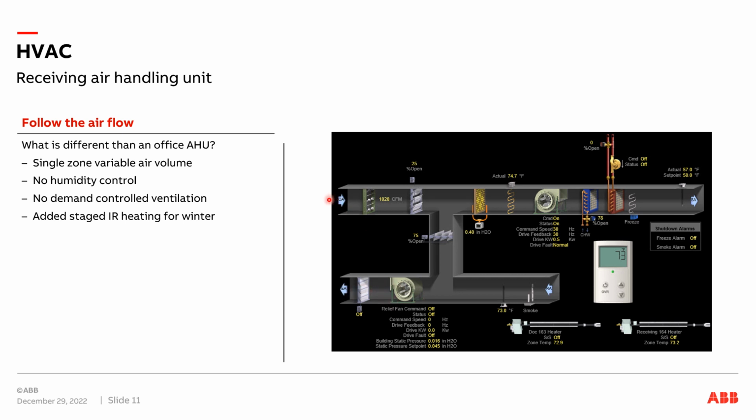So when you're bringing a lot of fresh air into the building, that air has to get out of the building somehow. Right now, with this being closed, I can probably tell that we have some big doors open and a semi-truck backed up, so there are other ways for the air to get out of the building. Had this been open and this fan been running, that would have told me all our garage doors were shut, so we needed a different way for the air to exhaust from the building.